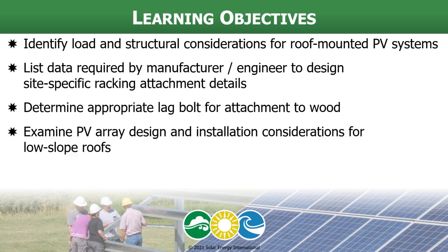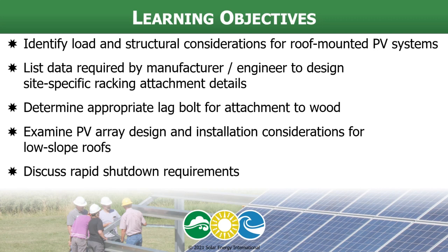that situation. We're also going to look at how we calculate the proper size of a lag bolt when we are going to be attaching our racking system to a wood structure. And we'll take a look at some design and installation considerations that we need to think about when we are using a system on a low-sloped, often commonly referred to as a flat roof. And finally, we're going to review everyone's favorite topic, rapid shutdown, and what those requirements are for roof-mounted systems.